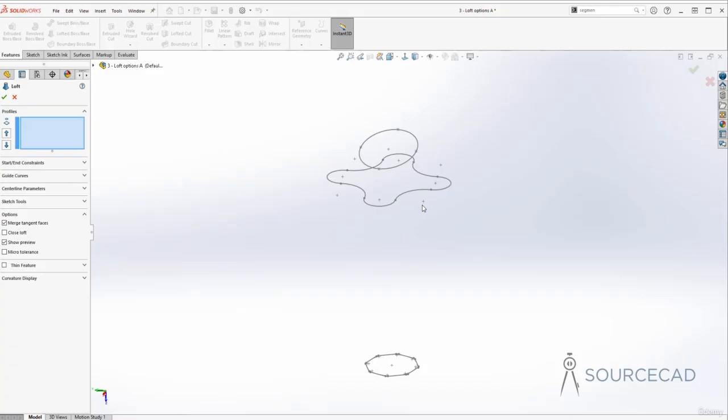But it's not always possible to have equal number of segments in the sketches. For example, this last one is actually an ellipse, and here, as you can see, we've got only 4 of these points. So of course this is not made with 8 separate segments. Now for this kind of geometry, you can create segments using the segment tool, and you can add your own points here. Let's do that first before we convert it into Loft.